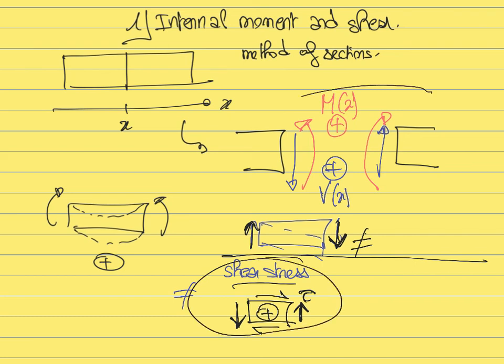And then you have the sign convention for the internal shear, which is also this one. Despite the fact that they are opposite to each other, those are still the ones commonly used. So one thing to remember is that a positive internal shear will result in a negative shear stress, due to the fact that those two sign conventions are opposite to each other.